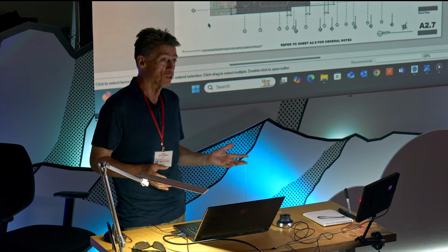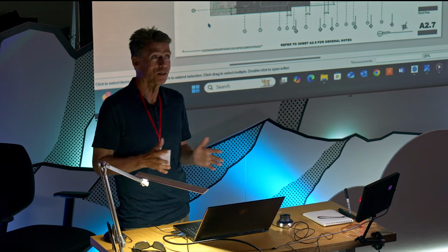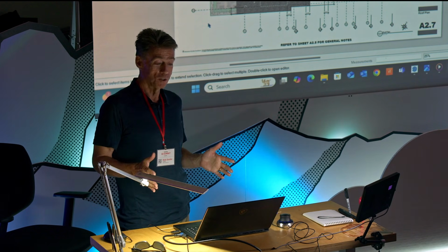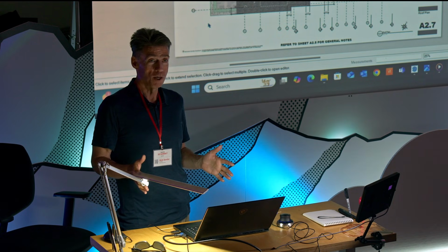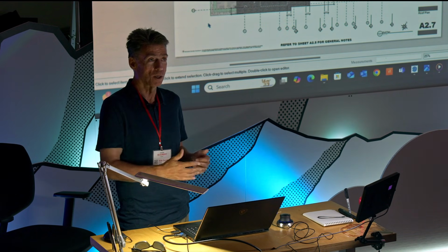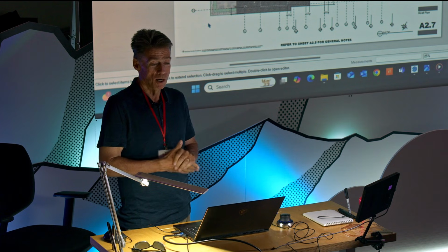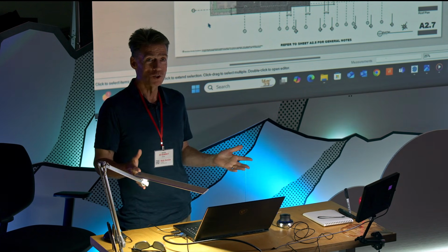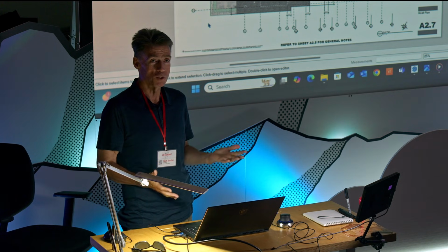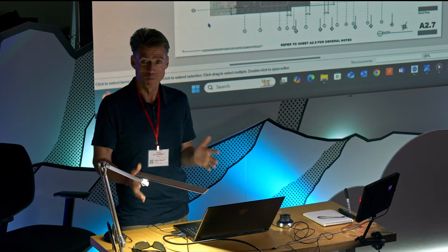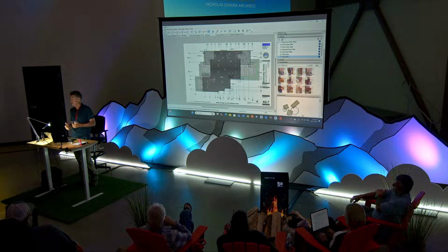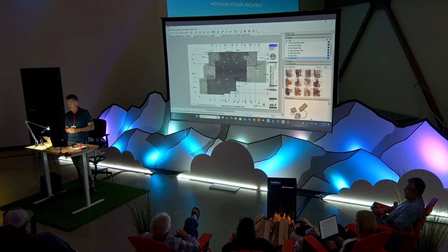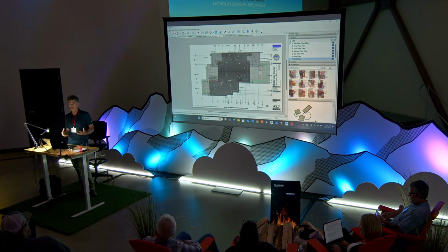For interior designers, and I know there are some in here, I keep a separate file for interior design, for interior elevations, and that again is all section cuts. The main reason I do that is the number of section cuts I'll put in a single project is probably in the 50 to 60 range. If you've ever looked at a model with 50 to 60 section cuts, it's a nightmare to manage. You have to manage it through tags or something. For me, it's just been easier to have these separate models.